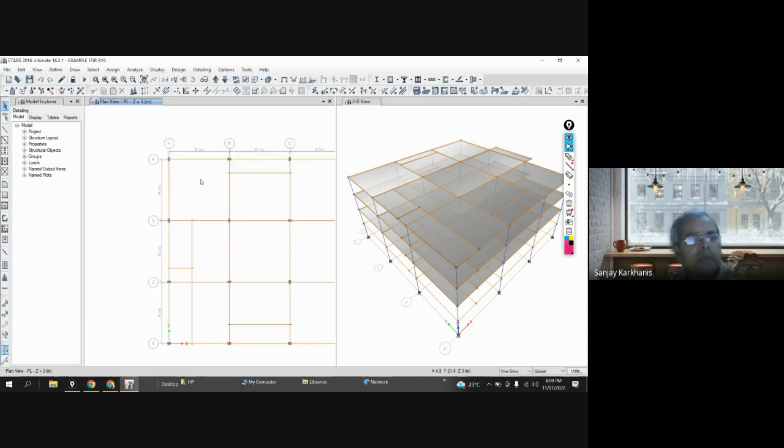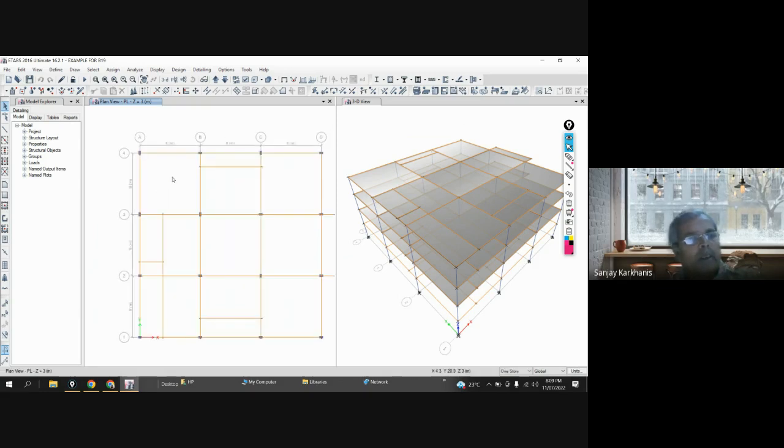Now, you are going to apply that loading on all the beams which are carrying vertical walls. Let's say I'm selecting these 4 beams, then these beams. Let's say I don't have loading on these beams. Then there is a beam on this side, and these are the beams that are carrying the loading. So I have selected all beams on which I want to assign SDL.